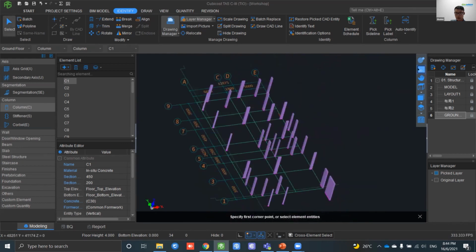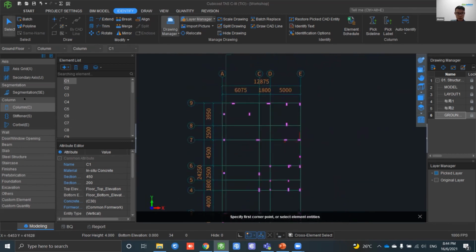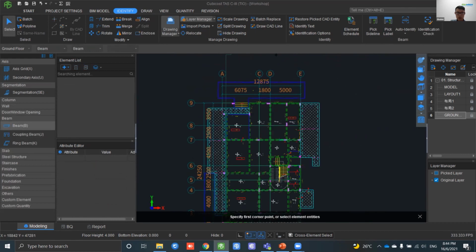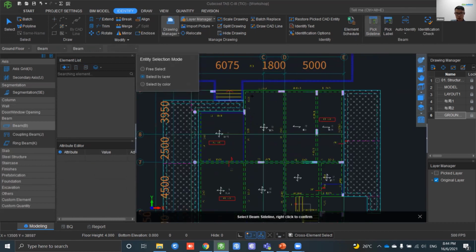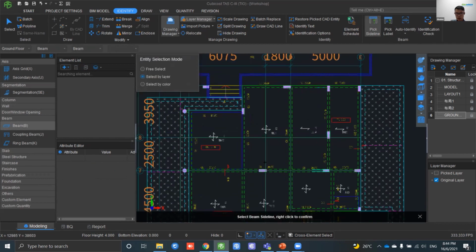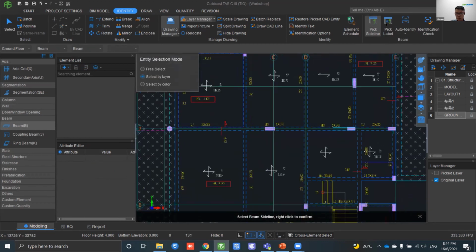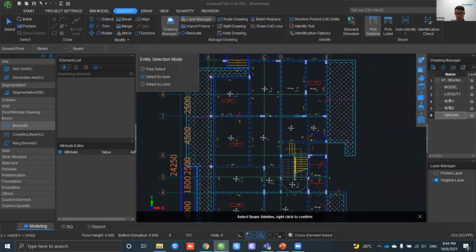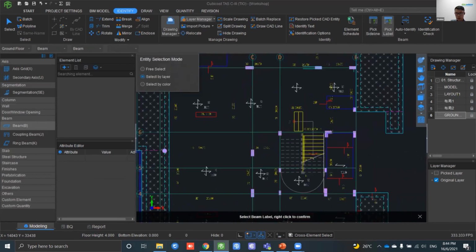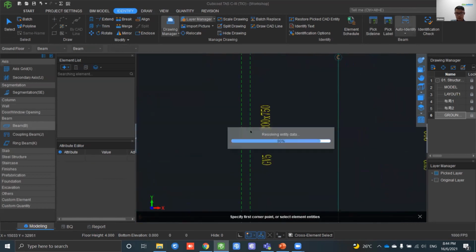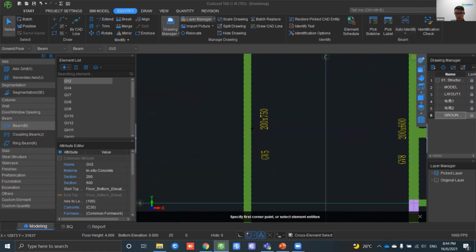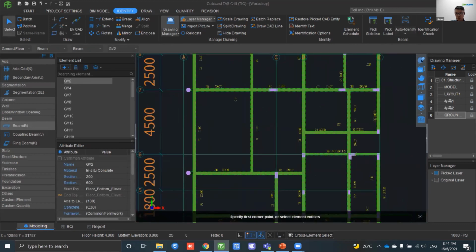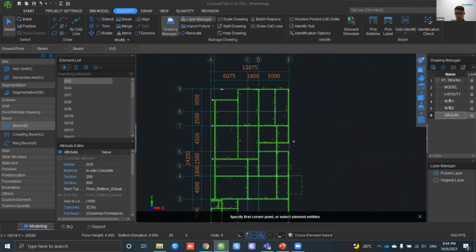Okay. Then moving on, we have BIM. So BIM works the same as well. So again, we pick the sight line, make sure that we pick all of the required sight lines. Then we pick the label. Then we use Auto-Identify. Once we are done, we can double check by using the 3D view again.